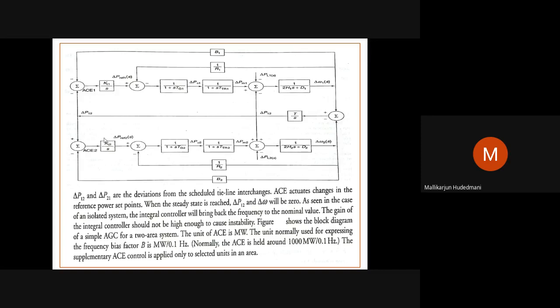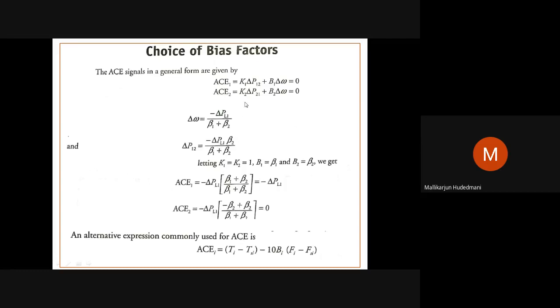Therefore, I have just made you aware of how ACE makes an area respond to a certain change in demand and change in frequency, as seen by the incorporation of supplementary control into the area's control system. So this should make you comfortable. Yes, there is a change in load of a certain area, and that area's ACE is going to be compelled to initiate the action. So this way, I just stop here. In the next class, we go ahead with the